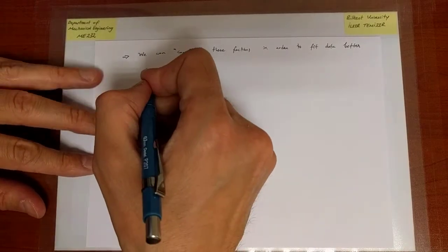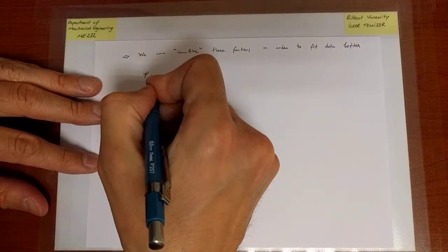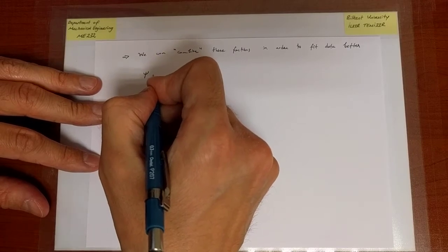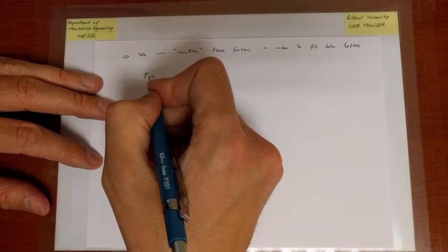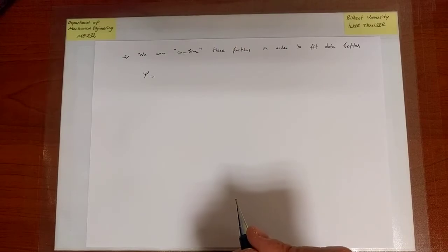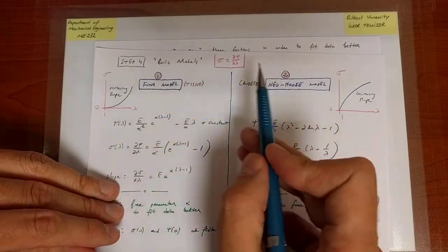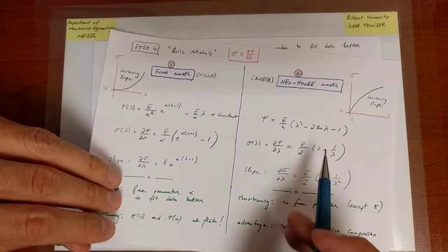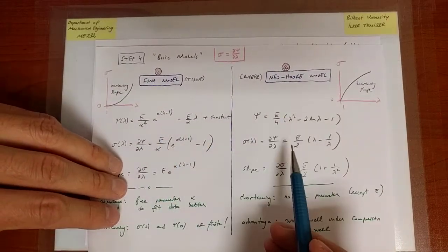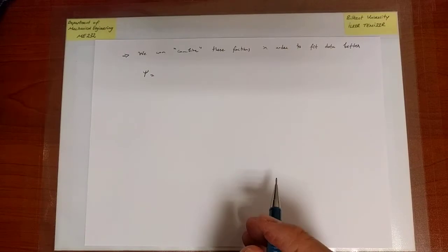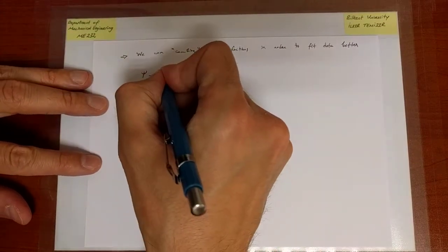Well, I want to propose a strain energy function that is neither the Fung nor the Neo-Hook model. We just called Fung the first model, remember, and Neo-Hook the second model, so I'm going to refer to them individually with an index of 1 or 2. I want to combine them in a very simple manner, mixing them through a parameter beta.